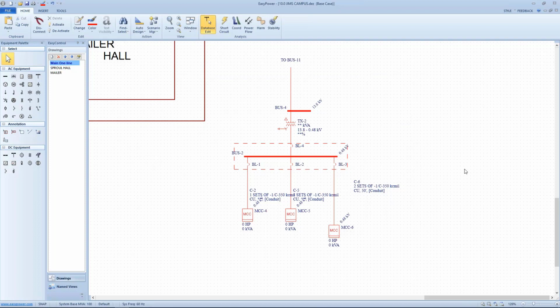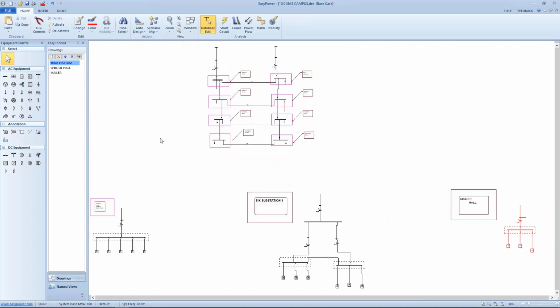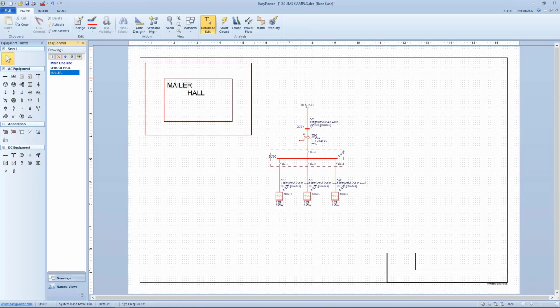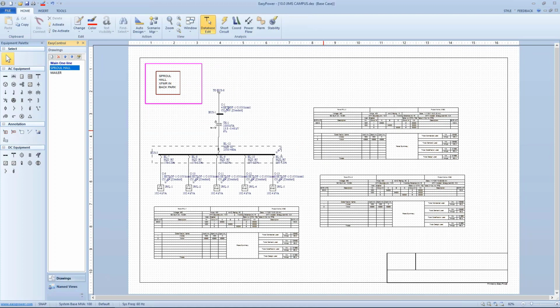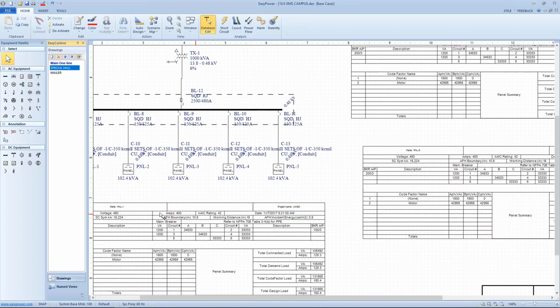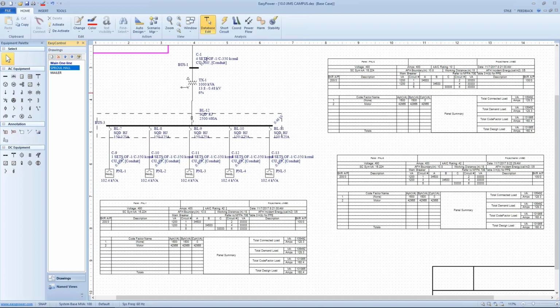Okay, so what have we done in our 30 minutes here? We've looked at the utilization of a OneLine diagram that lets me eliminate a spaghetti ball display. I can isolate specific panels, both in their own drawings, and I can include schedules that can be customized to include more data than just the default information on a schedule. In this case, we included a short circuit fault current and the arc flash information for each of the panels inside the schedule. And as we go to our named view, because I want to start with my OneLine,